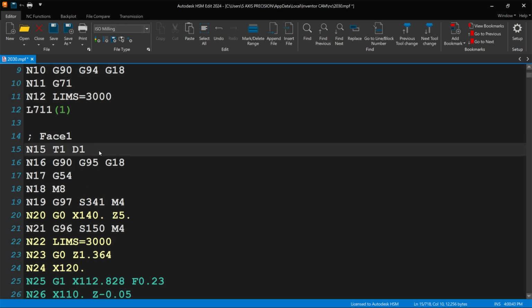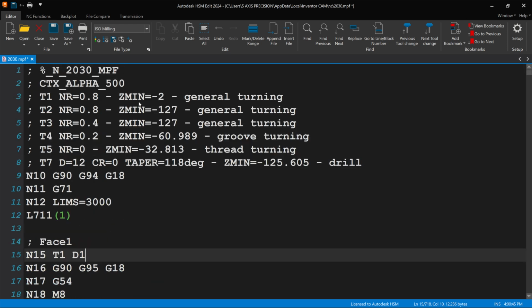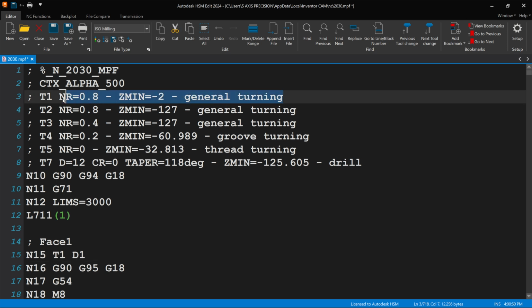You see now it is using the actual tool, and you see from this tool I'm using this, so I can initiate this one to say this tool T1 is CNMG 120408. Then I can put dash OD for naming, so that somebody can use this tool for naming. I can say OD RAF 80-08-L, so that somebody is able to know the tool they're using.